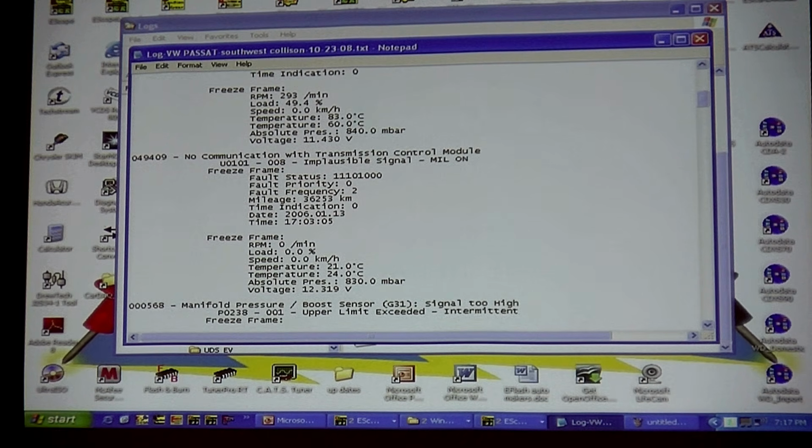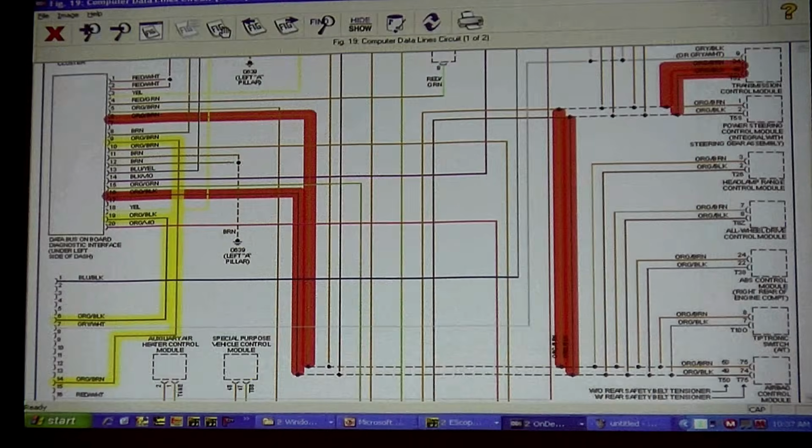But we can already see that I can destroy another module's message, and I never even got tagged. Be really aware of how this is going to work. And I can destroy messages all over the bus. I have codes from everybody. Now, really, what's wrong? How do we find it? We're going to go in and look at low and high-speed buses. We're going to get all the data. Make sure that you write your codes down or take pictures on your scan tool, but make sure you know what they are.